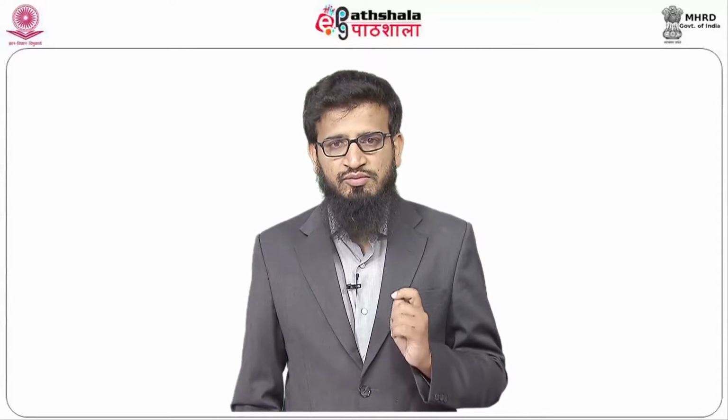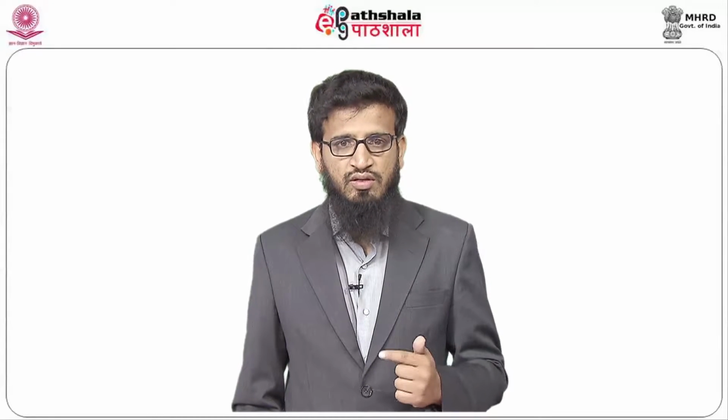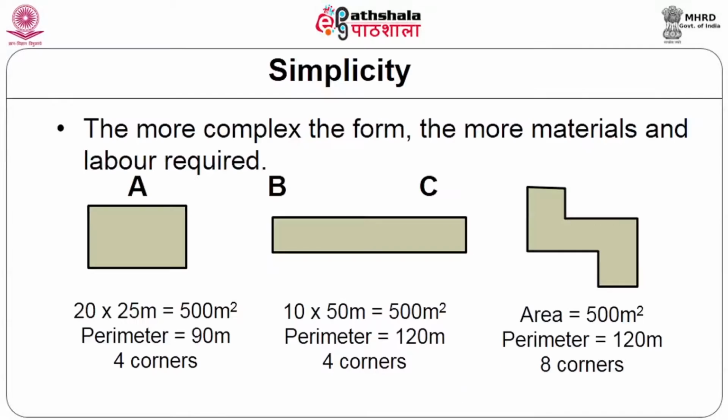The more complex the building is, the more material is required, there are wastages, and labor is also required, which means that it will increase the embodied energy. For a simple example which I have given over here, A, B and C. A is just a rectangular box, perimeter 90 meter, 4 corners. When you look at B, which is more stretched out horizontally, it is the same square meter. All three are of the same area, but the perimeter of B increases by almost 30 meter, which means there is more material required in it.